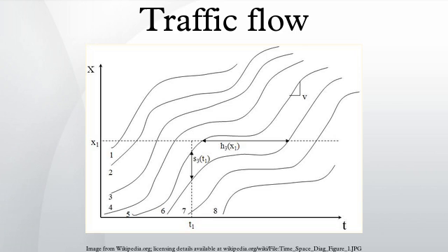Stationary traffic equals. Traffic on a stretch of road is said to be stationary if an observer does not detect movement in an arbitrary area of the time-space diagram. Traffic is stationary if all the vehicle trajectories are parallel and equidistant. It is also stationary if it is a superposition of families of trajectories with these properties.